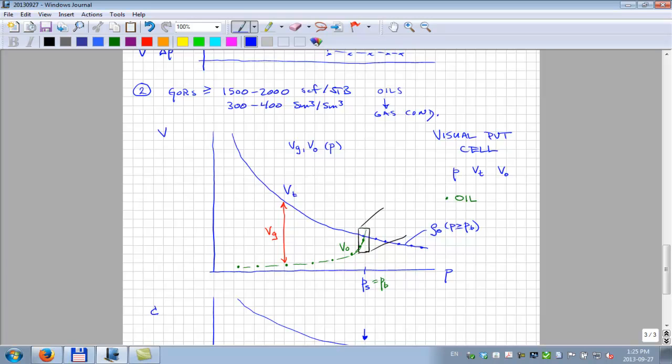That's right. But how do you put this? Okay, you're doing this test from the pressure close to the reservoir one, or whatever you're interested in, down to the surface pressure, like standard condition? Well, typically you have to stop where this volume here is typically around 4 times what you start with. It's usually 4 or 5 times. But the point is to fill this cell with this oil, with dissolved gas.